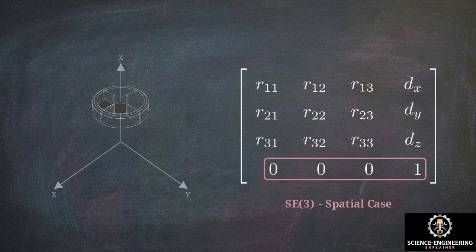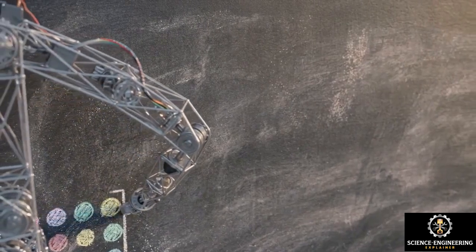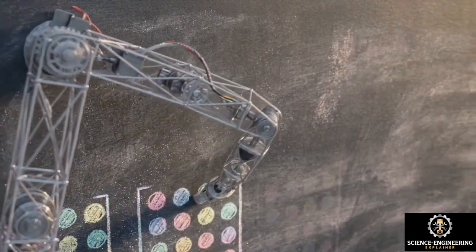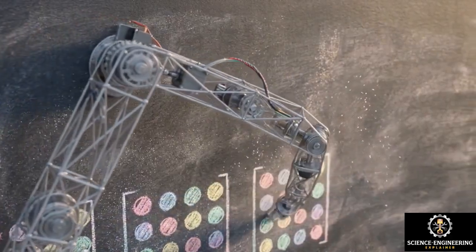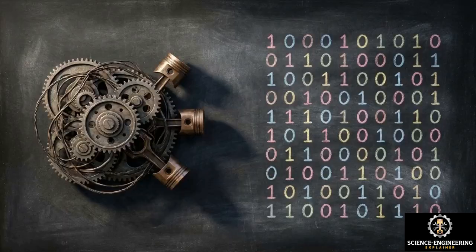Now, to map the exact Cartesian location of a robot's tip, engineers can simply multiply the matrices of each individual joint sequentially down the chain. The Homogeneous Transformation matrix takes the messy physical geometry of pivoting hardware and converts it into a clean, highly scalable linear algebraic pipeline. That scalability is tested in complex environments where independent agents share a physical workspace.